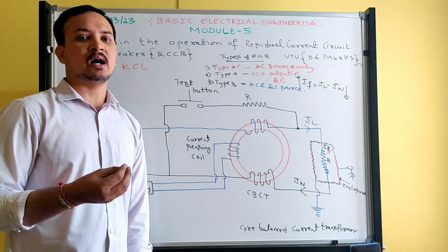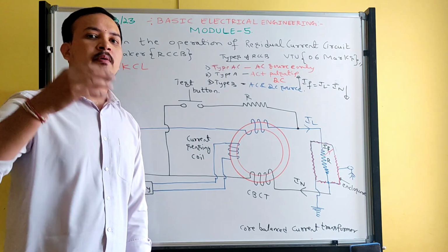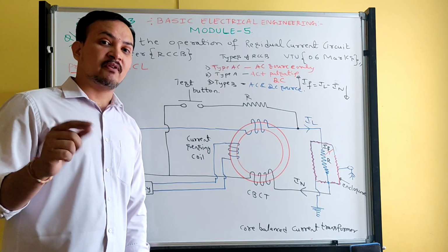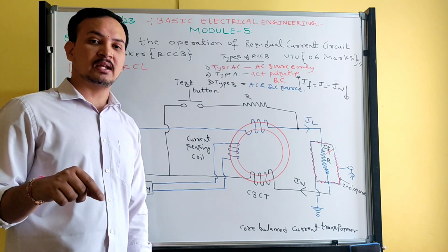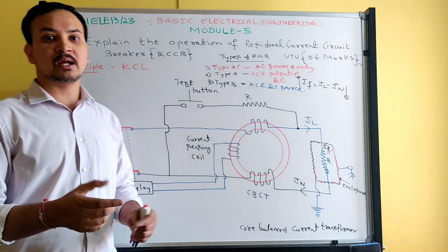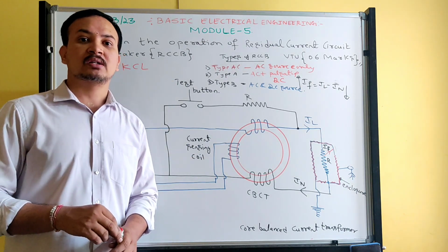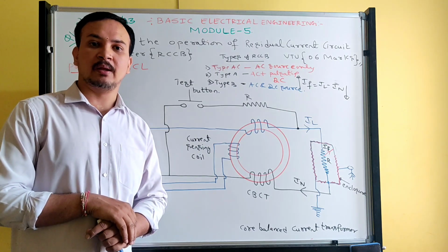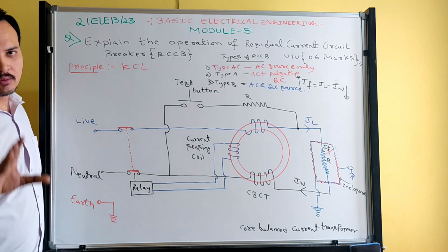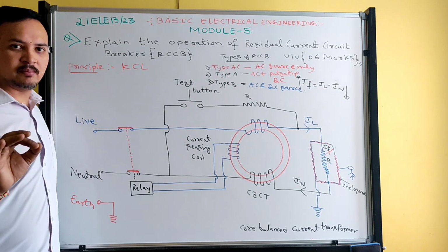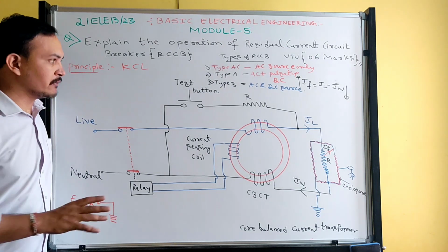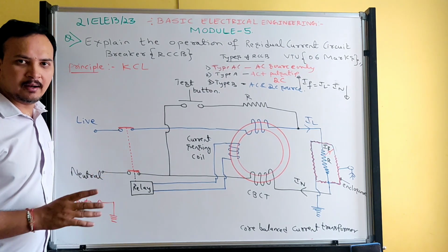If you connect MCB after RCCB, MCB will trip for earth fault and short circuit. But if any fault occurs due to earth leakage current, then RCCB will not trip, because MCB trips, supply gets disconnected. Okay, but still supply is connected to the RCCB. So there is some clear-cut clarity. You must always use MCB before RCCB. Understood, guys? I hope everyone understood in detail.